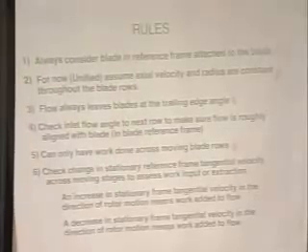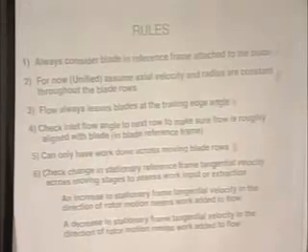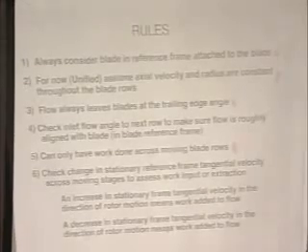You've taken swirl out. So the purpose of these rotating blades is to put in swirling kinetic energy so that the stationary ones can convert it into internal energy, and you go on and on and on. All right, before I go ahead and do an example, questions about that stuff?